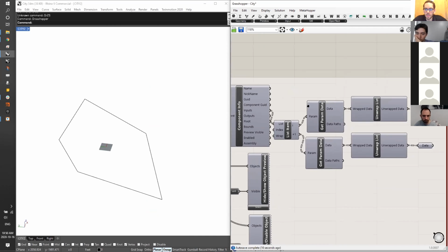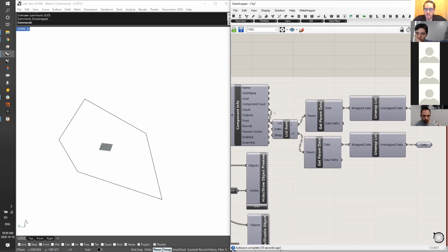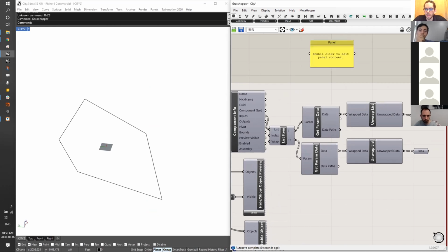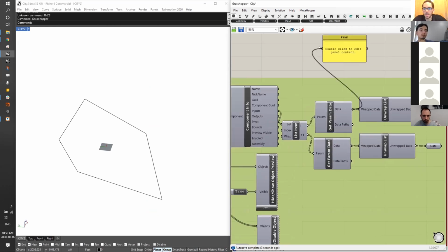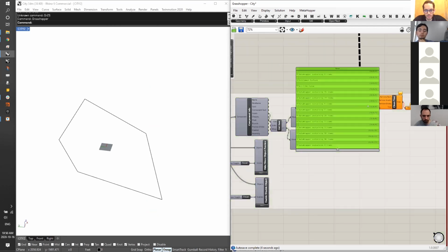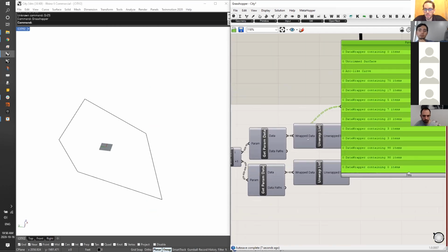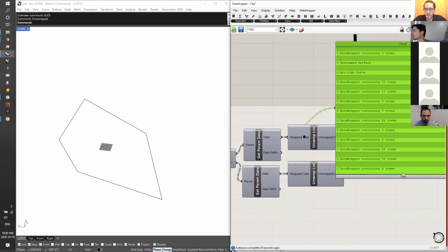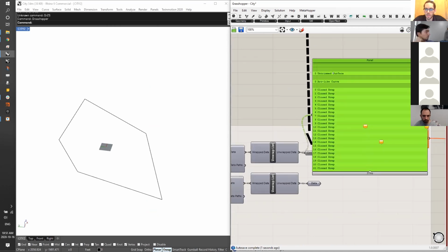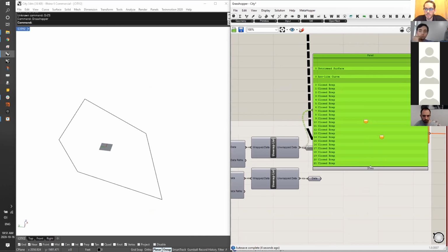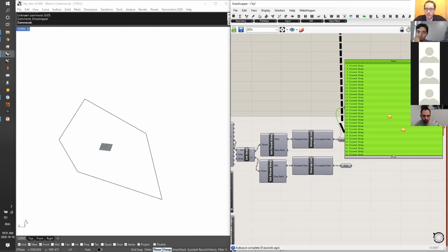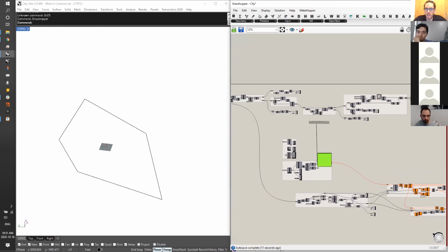So in this case, I want to get that particular piece of data and then extract what geometry is inside that kernel, right? Some of them are wrapped, so they're data wrappers. If you ever come across that, you can simply unwrap them using the built-in unwrap list component. If you have a piece of data that is already unwrapped, it's okay. It's smart enough to understand that, and if there's nothing in there, it'll discard it. But this way, it's a way of communicating with your script without having to physically zoom in and out constantly and pan around.